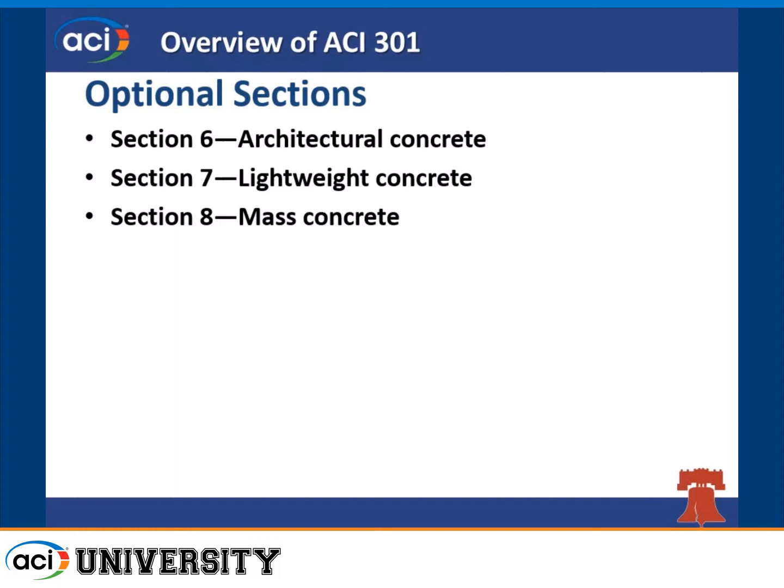We also have section 8 on mass concrete structures, and there were significant changes in the last 2 cycles on this. When I first joined 301 back in 1999, when Cal was our chair, we had provisions that were very basic in the mass concrete section of make it 70 degrees. We'll be all happy. But in Florida, other states, that's not necessarily the most economical way of doing things these days.